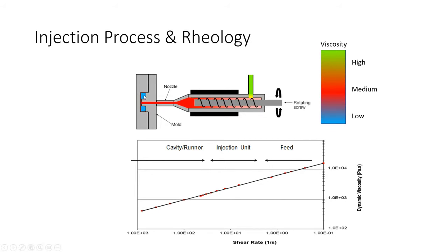I made this blue to represent water, because really we're approaching the viscosities of water in the injection molding process. But we start with extremely high viscosity, and the injection machine's duty is to break that rubber down through heat and shear and drive that material into the hot mold surfaces to get it cured properly. We want this process to be as consistent as we can, heat to heat, lot to lot, day to day, shift to shift. Material characteristics will give us an insight into the performance of the material and what the machine has to do to compensate.